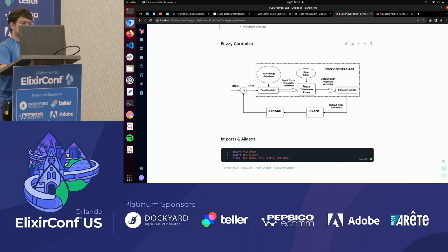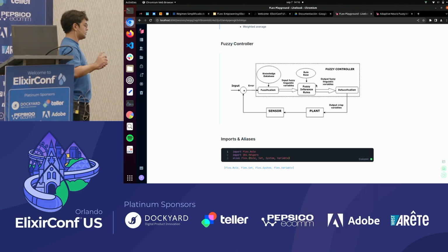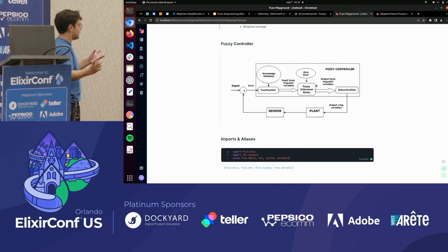So, how to design a fuzzy controller? Well, the schema that I show you here is basically what we were talking about on the previous slides. The catchy thing here is that we are going to have, as an input, the set point of a desired variable. Since we can have a feedback, we can compute the error of how the system is behaving.